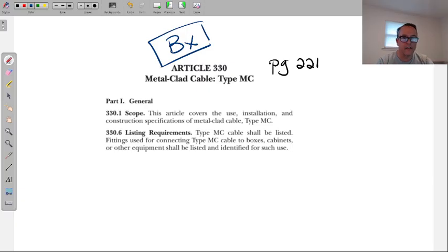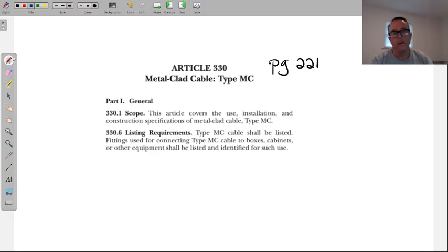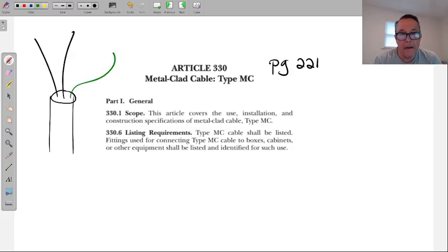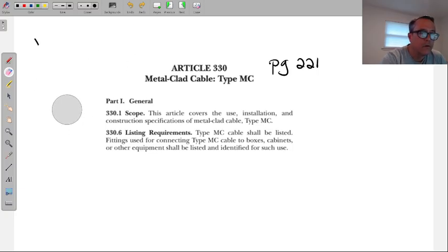Metal frames, not a good idea to run Romex. We are allowed to run Romex through metal studs. You just got to use bushings and grommeting and all these other protecting factors for the Romex. So when we're in metal, we like to use a metal flexible cable, and MC is the new type that everybody's using. The biggest difference is that AC cable has a bare copper ground, like Romex, whereas MC cable has that insulated ground conductor, which we just prefer a lot better for this conductor.